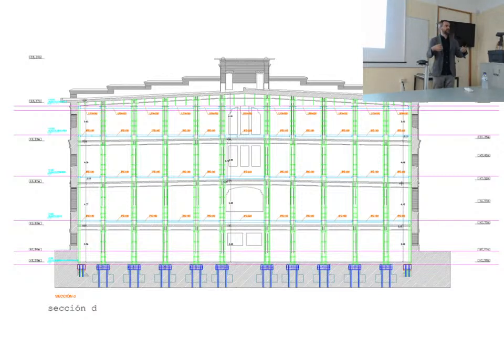or even increasing the section of the existing concrete columns, we came with this idea of why not to build like new steel columns, but not attached to the existing ones, in order to be able to view the existing sections. And instead of strengthening the existing structure from below, why not to build a new level on top of the existing one that would be able to resist this additional load, this 5 kilonewtons per square meter, and transfer directly all these loads through this new structure. So the existing one will only need to support itself, okay? This is like the key idea.